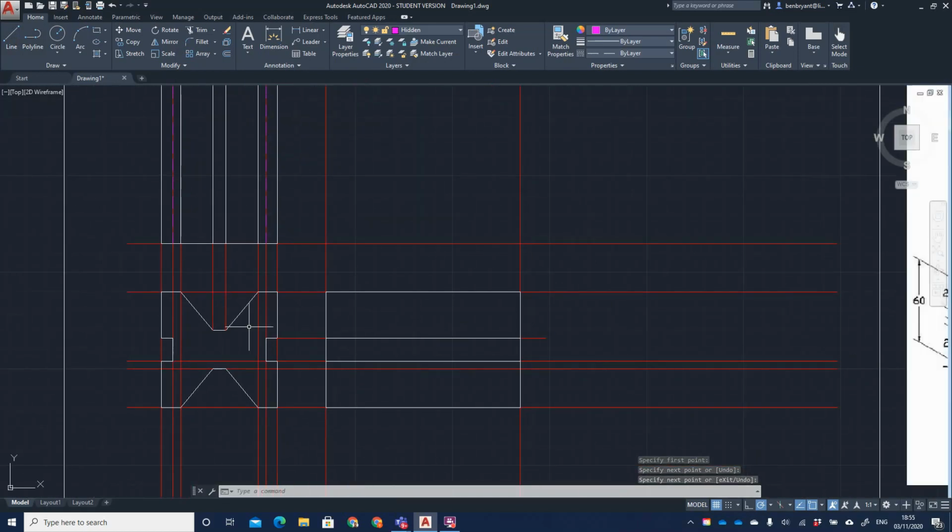So same again, I just need to put the hidden detail in on this side. So again, I can then run along. Now again, I can either put a construction line in here, or what I can do is lock onto the feature and just quite simply run along, referencing the snap points, because obviously I mirrored the top, so I don't have the construction line to replicate it, but I can quite simply just run along the side very, very easily.